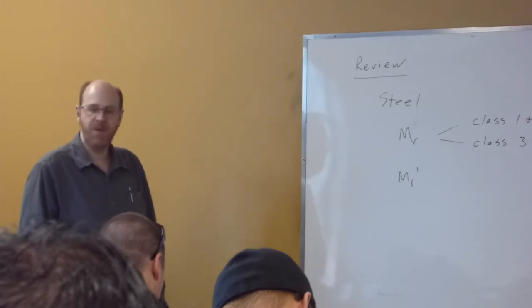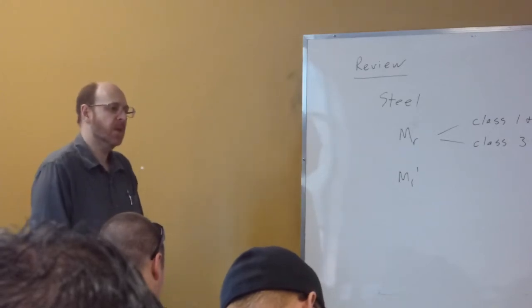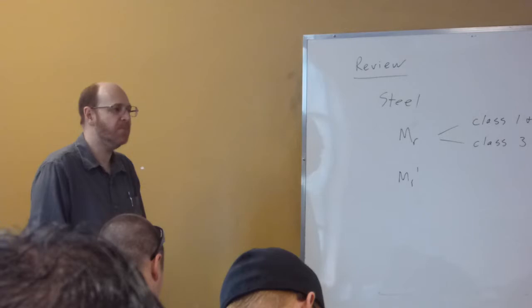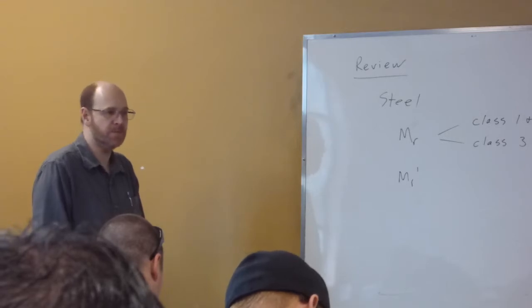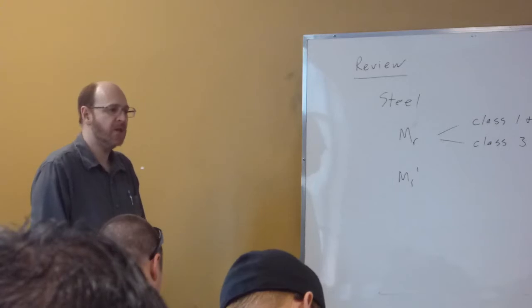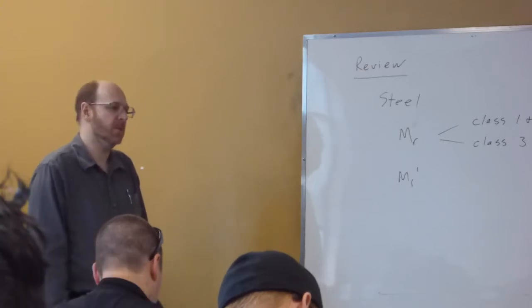One is if I happen to have a really short beam. The second one is if I have a point load applied very close to the support, which creates a high shear but not very much moment. And the third one is if I'm cutting holes in the beam.